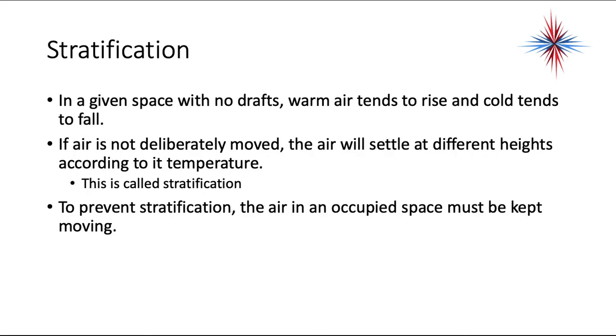In a given space with no drafts, warm air tends to rise and cold air tends to fall. This is called stratification. If the air is not deliberately moved, the air will settle at different heights according to temperature. To prevent stratification, the air in an occupied space must be kept moving, because again, you're going to have different levels of comfort. Cold air will fall, so we don't want all the air-conditioned air just to be around the floor, because most people will feel that cool on their feet, but the rest of the body will feel warmer. So we have to actually move the air in conditioned spaces.